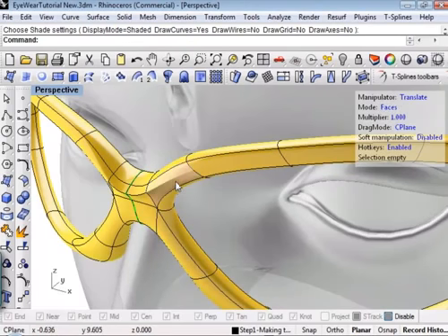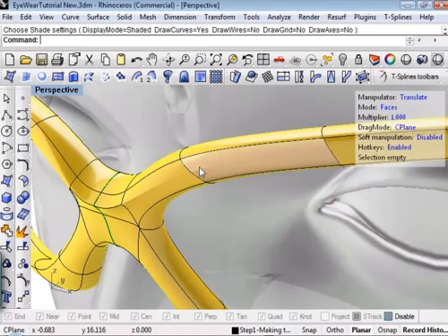Here's the first face, here's the second face. My crease started here, went all the way through this face, and went halfway through this face before it dies out. Creases need 2 adjacent faces to disappear.